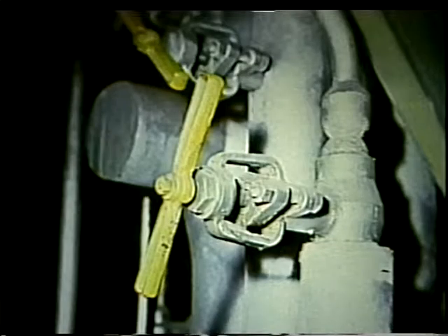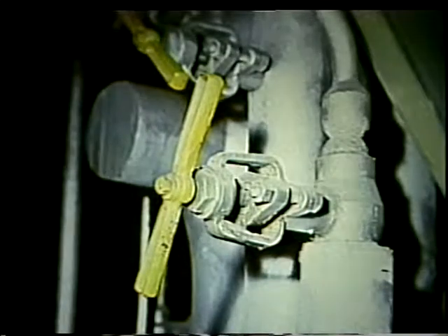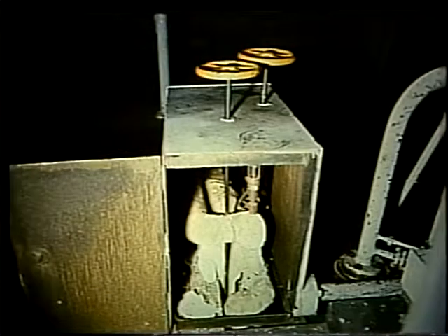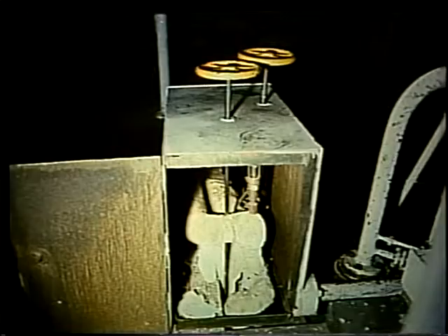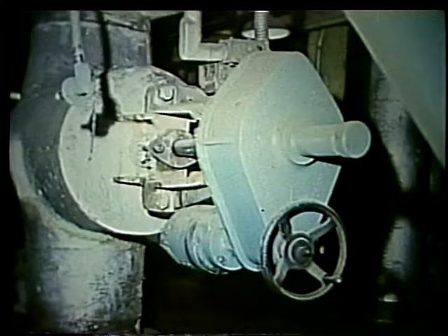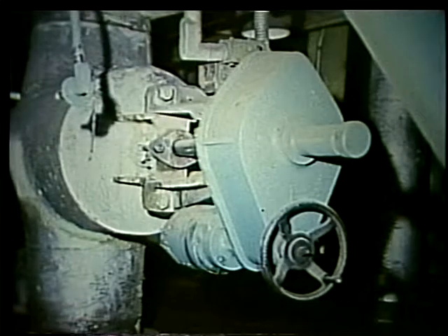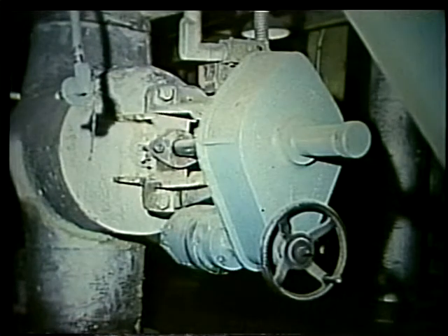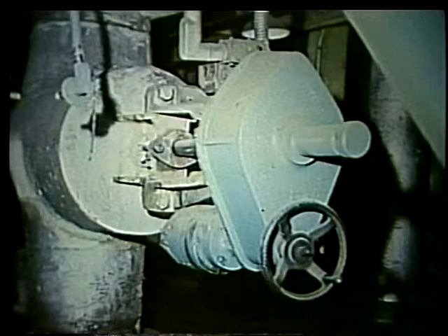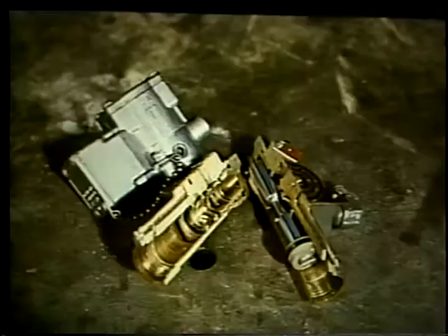Hand wheels can be equipped with other types of adapters to make them easier to operate. Sometimes a chain running through a pulley is attached, or an extension arm might be put on the hand wheel of a valve that's hard to reach. Motor-driven operators are often used in place of the hand wheel. Electric, hydraulic, or pneumatic motors provide ease in handling, and they allow remote control operation.